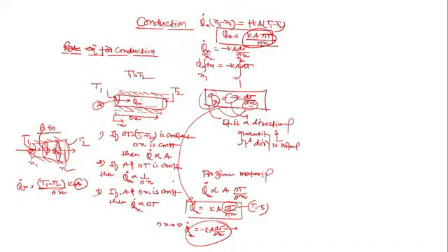So you can't write it over a finite area, sir. That's why I can write Fourier's law as q_x equal to minus k A_x into dT upon dx, only over the small differential element, when dx is very small and the drop is dT. Only over the smaller element where dx tends to 0, in that differential area, can I write q equal to minus k dT by dx.